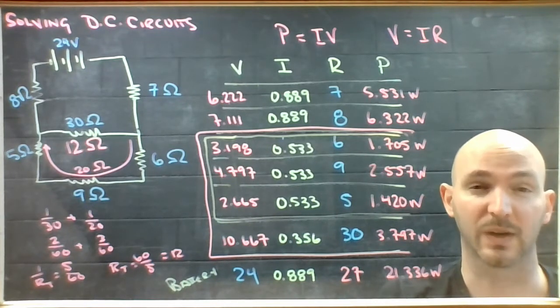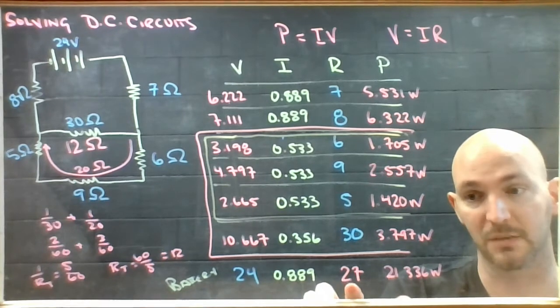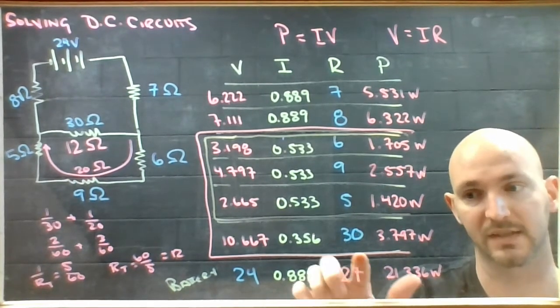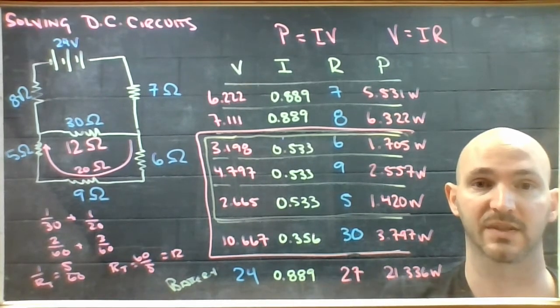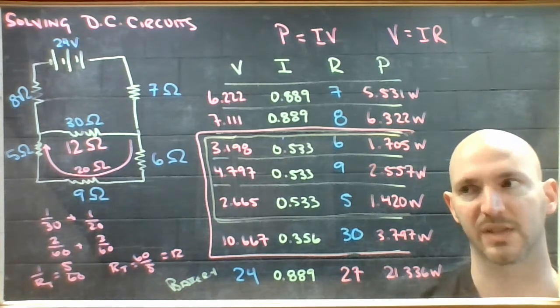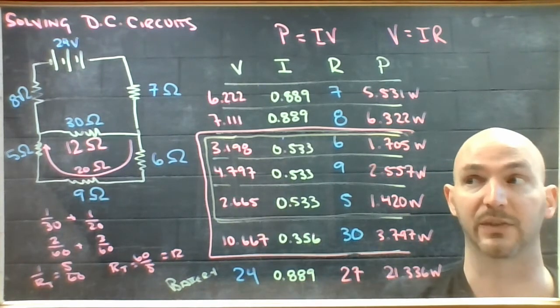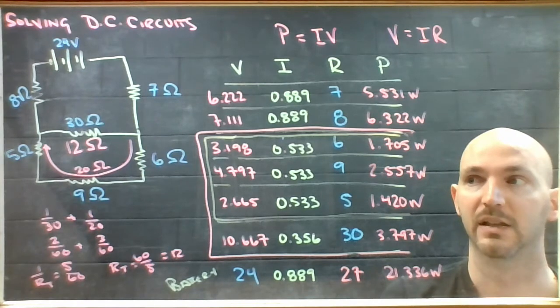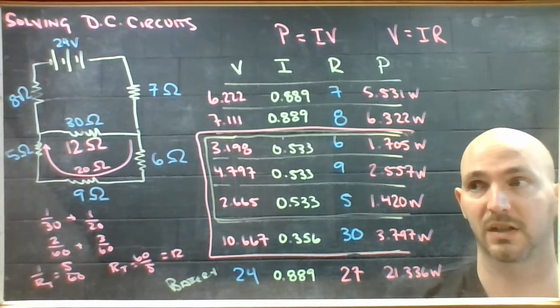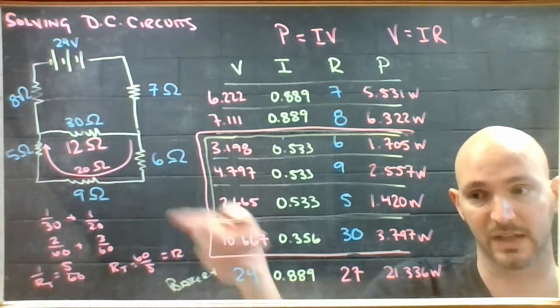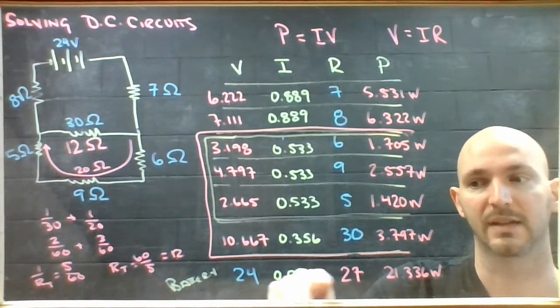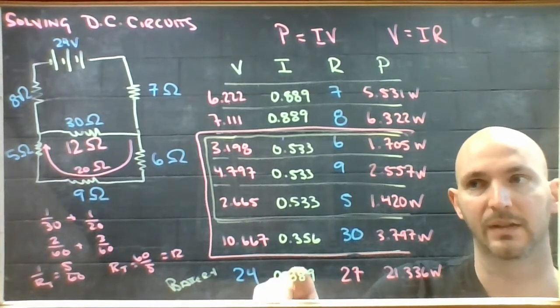But really the trick to this was getting this number at first, right? This total resistance of the battery. That's the place you always have to start, which is why we spent so much time in the last section hacking through that and making sure you could do it. So if you start with that with each problem, collapse the whole monster pile of resistors into a single total resistance, and then get your current, and then you try and puzzle